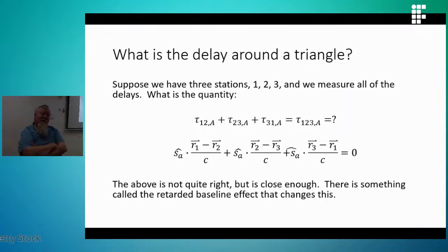Okay, going back to this slide here. If I go all the way around the triangle, I find out that the delay should be 0. A couple of comments: when I measure the delay, each measurement has some noise in it. So if I actually add up all of these numbers, they're not going to be 0, but they should be close to 0. So this is one check that your stuff is working okay.